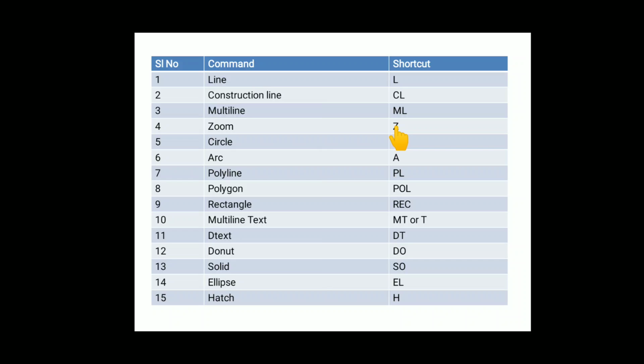Then it also has a layers concept where you can draft one part of a drawing completely by creating one layer, then above it on the other layer by creating a second layer. So you can move or edit or make any kind of alteration for one particular layer without causing any difficulty to the other layers.